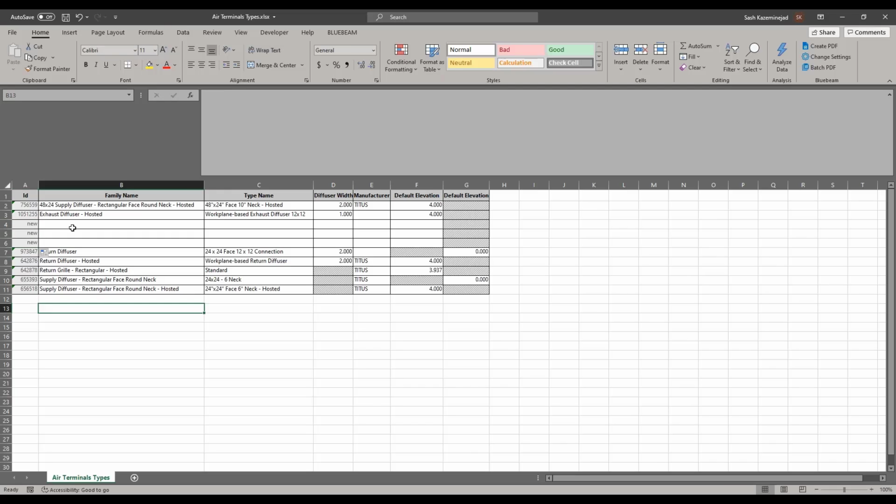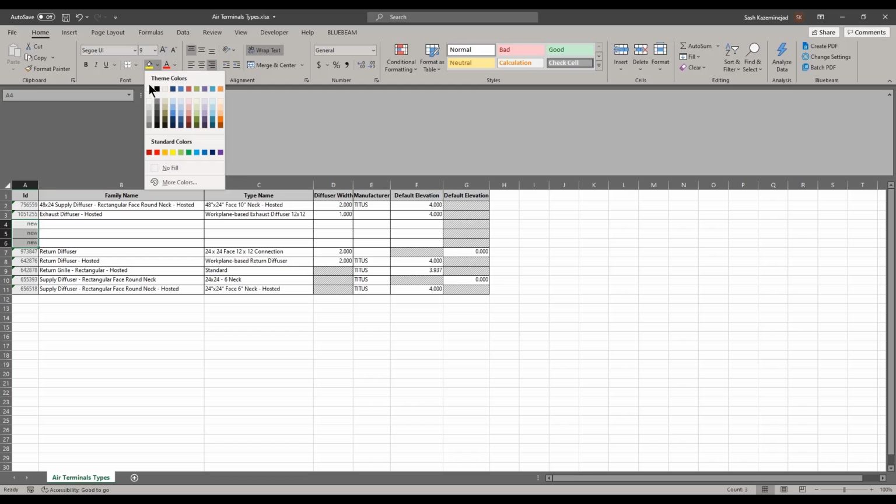By the way, for those of you that use BIMLink a lot, you know that white fields mean they're editable and gray means that they're not. In the case here, where I just inserted these new rows, these were gray. If this bothers you, there's no harm in changing the fill color to white, although it's not going to make any difference. BIMLink is going to understand what to do here. If it's just a graphical thing for you in this instance, feel free to change it to white. Changing this to a white fill doesn't mean it's going to become editable. Just something to keep in mind.